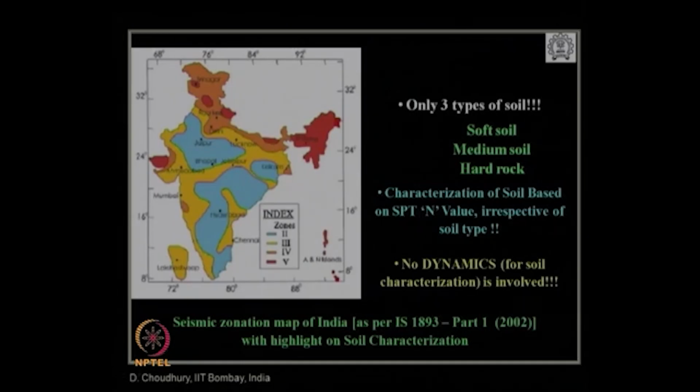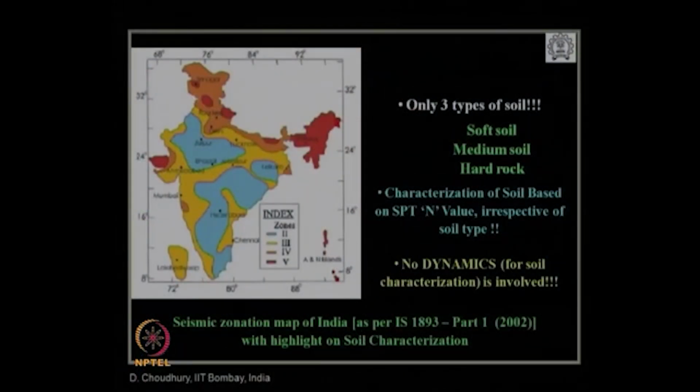And to come up with this seismic zonation map, the major criteria are to identify the effect of the earthquake, and also how to determine values like peak spectral acceleration, etc., depending on the soil type. Those I have discussed in the site specific ground response analysis. Obviously, the code cannot give individual site specific values, but it has to give a broad value which will overall match a design suggestion for regular buildings, and considering the importance factor, etc., for important structures it can be considered.